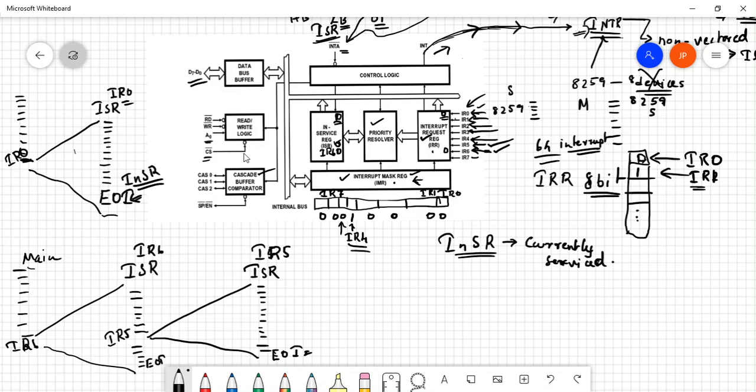I think we have already discussed memory mapped IO and IO mapped IO. So in that you can have any of the configurations where you can map this device using memory mapped or input output mapping, right? So depending upon the address, you will have to make an address circuit, which means that when that particular address is outputted from the 8085, the corresponding chip gets selected, right?